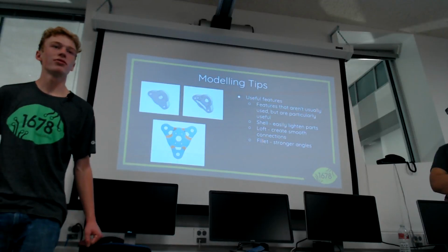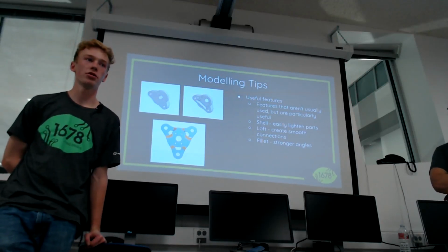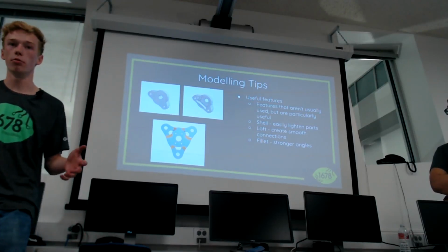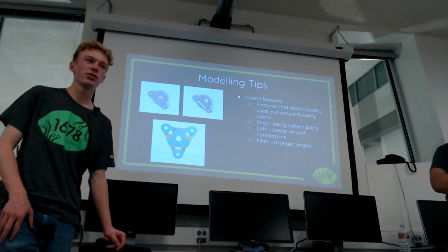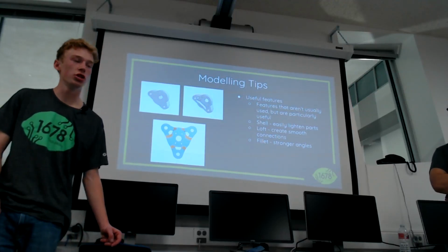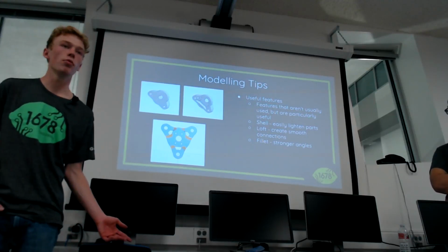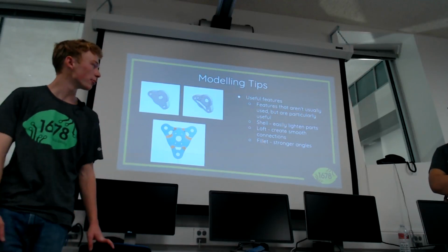Another cool one is the loft. I can't say I've ever used a loft outside of 3D printed modeling, just because it's kind of a weird feature. The idea is you make a connection between two profiles that you define. They make weird shapes, so they're not really suited for machining on a mill or a lathe. Of course, the 3D printer can handle them, so they're a super easy way to join a couple of separate bodies. You can just quickly define the profiles and join them together.